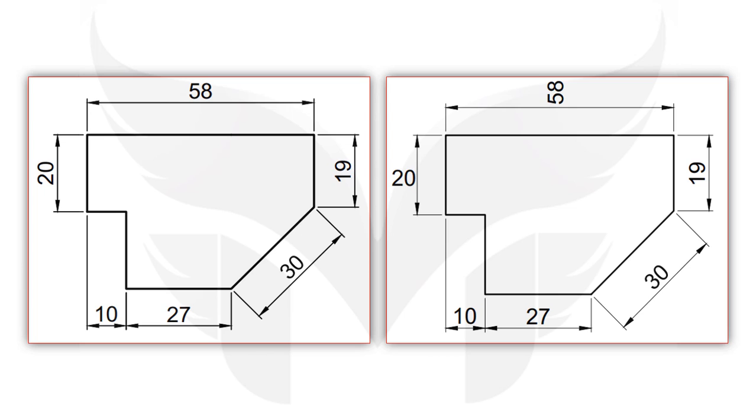So dear friends, remember that in the aligned dimension system, the dimension is always perpendicular to the dimension line and should appear above the dimension line when looked at from the front or from the right side of the drawing.